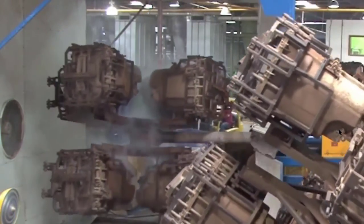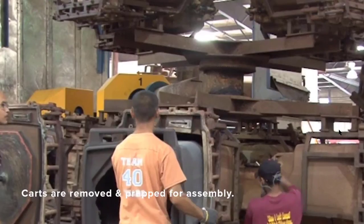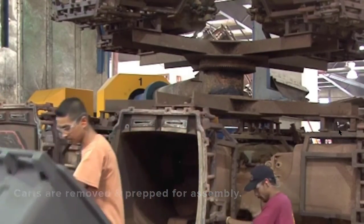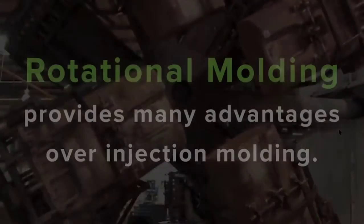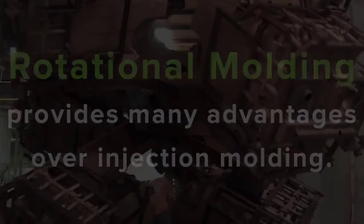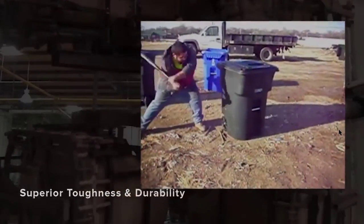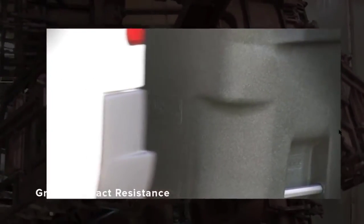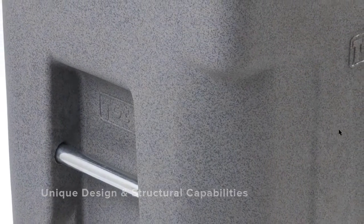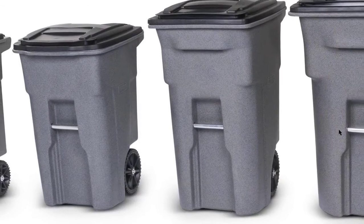After the molds cool and the parts have cured, they are removed from the mold. The parts are trimmed and final imprinting and assembly complete the process. Rotationally molded parts provide many advantages over injection molded parts, including superior toughness and durability, greater impact resistance, unique design and structural capabilities. The result is products built for extreme purposes.